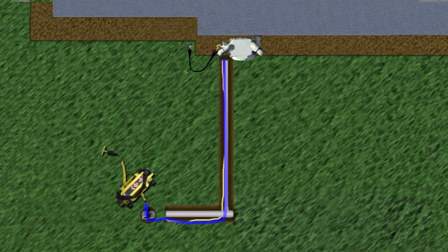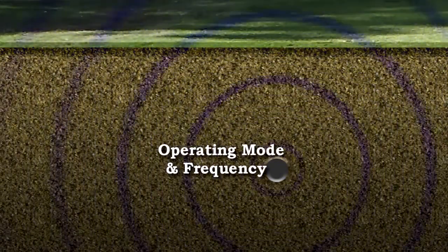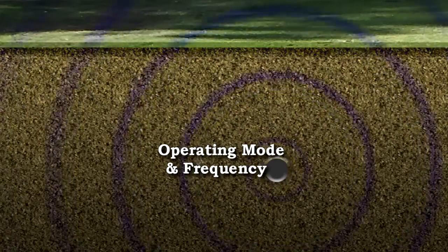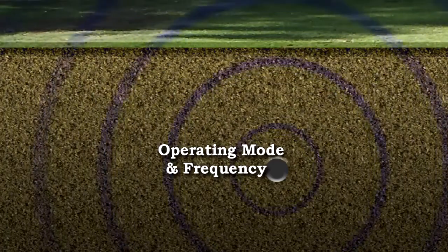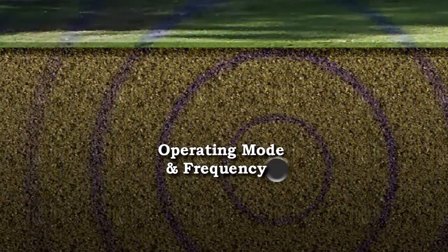When the transmitter is activated, it generates an alternating electrical current that flows through the conductor and back to the transmitter through the earth ground. This current flowing through the conductor produces an electromagnetic signal that can be detected by a receiver. When designating a utility's position, it's important to understand that the receiver is actually tracing this signal and not the utility itself. You are assuming that this signal accurately indicates the utility's location below ground.